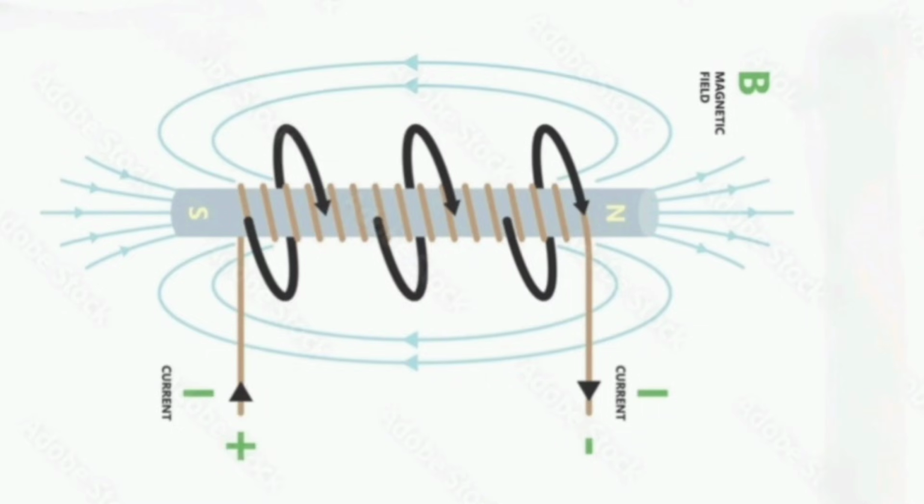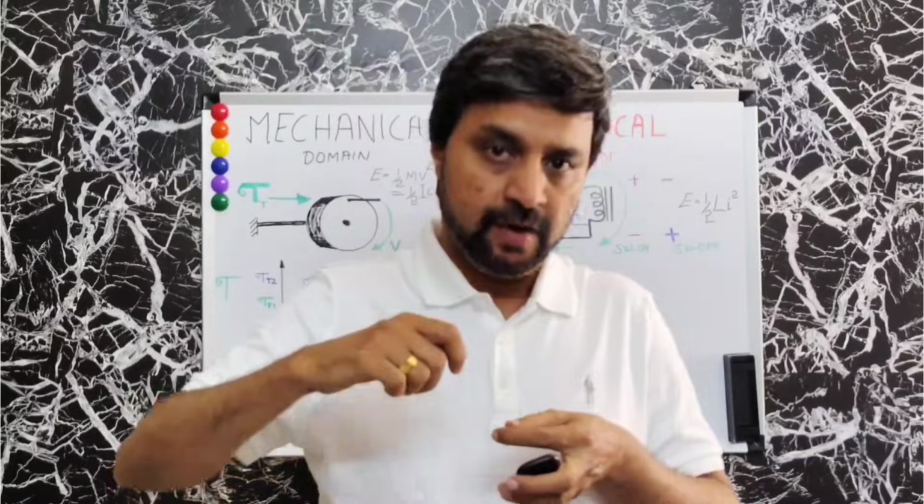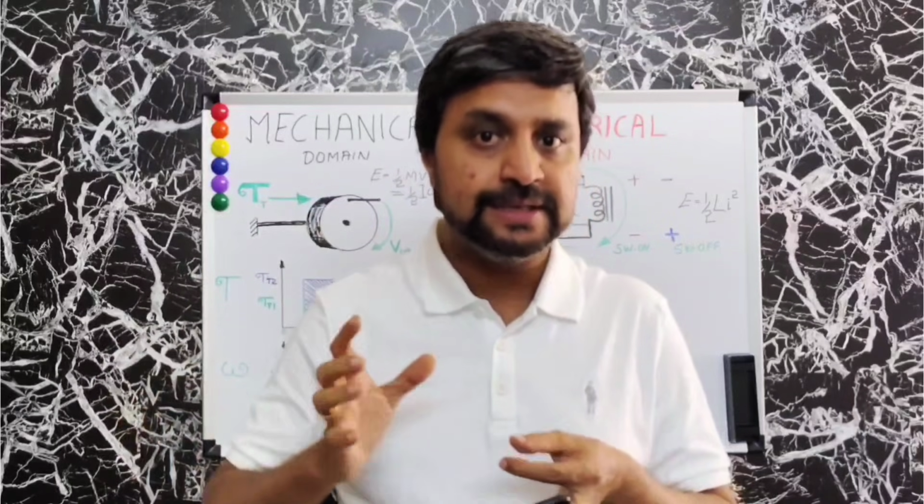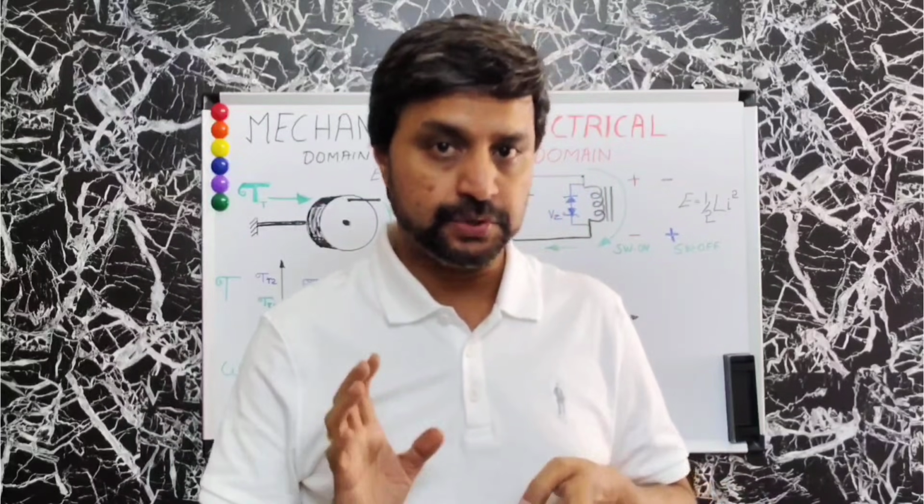If you carefully analyze this direction and polarity, you can see that they are additive when we wind it on a former as long as we keep the direction the same. If we change the direction, the polarity also changes. Ideally, when equal numbers of turns are wound in opposite directions, the net inductance becomes zero.